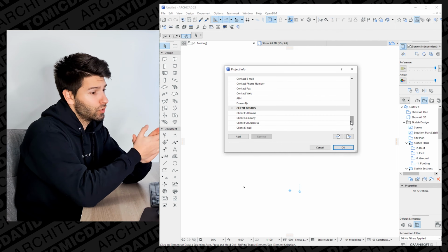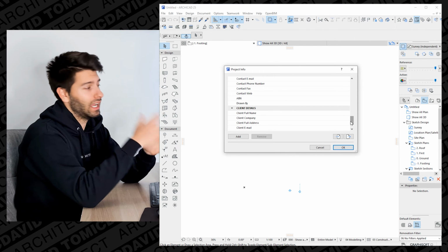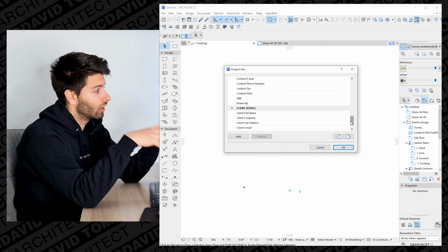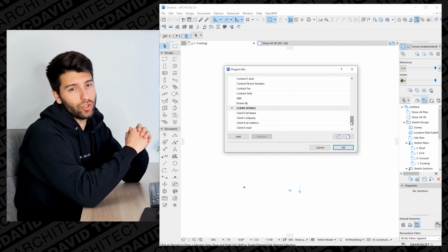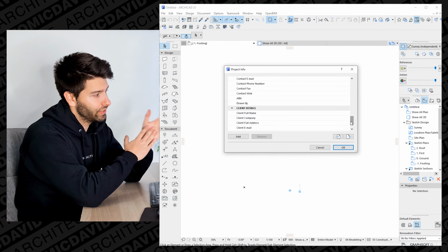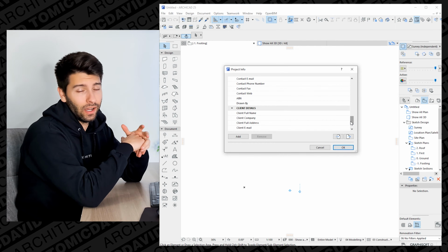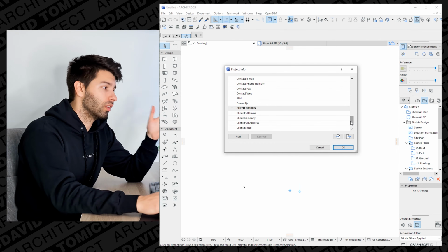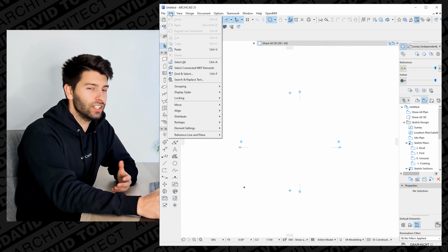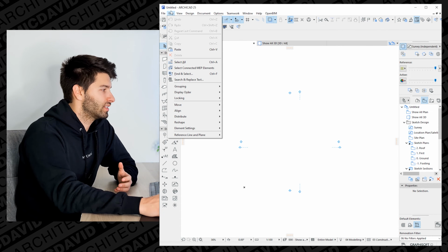That is very, very useful to anybody doing a title block. It means they don't have to go through every single page and change the client's name, the client details, the page numbers, etc. They can do everything in this one project info space and it's all done and dusted. Again, if you're starting at a new firm using ArchiCAD, this is something you're probably going to have to know, because this is exactly how you're going to change all of those company details for that project and import all that new information.